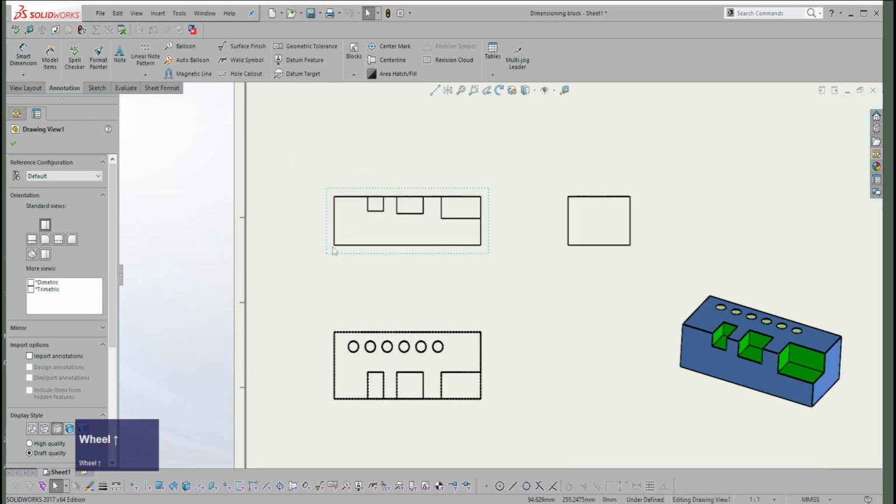Now we need to figure out where we're going to start from. And in dimensioning, the starting point is called the datum. So a datum just means starting point. That's what it means. So we say a datum feature. And now I need to decide where do I want to start dimensioning from. So I'm going to pick the left-hand side, the bottom side on the top view, and then the very bottom of this is my 3 datums.